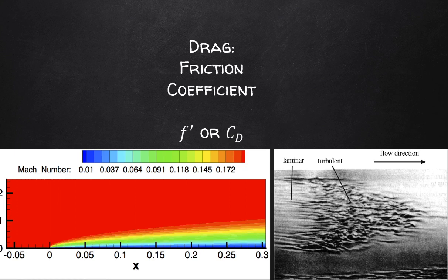Right, so flow across the surfaces of flat plates also has defined flow regimes. Now with pipes, we would typically have laminar flow throughout, or transitional flow throughout, or turbulent flow. But have a look at this picture and you'll see that the flow regimes actually change as you go across the surface, from the leading edge on the left through to the main surface of the flat plate, and as you leave it, you tend to leave with the flow being turbulent.